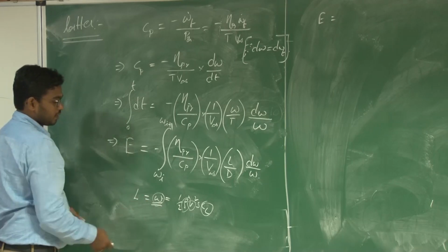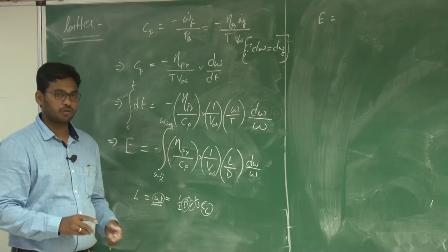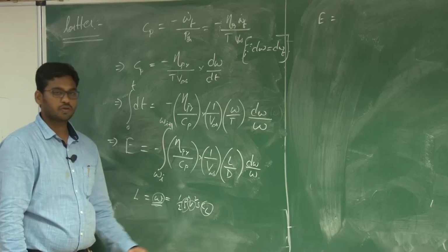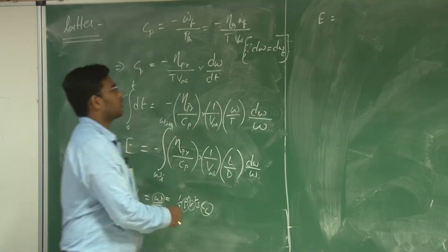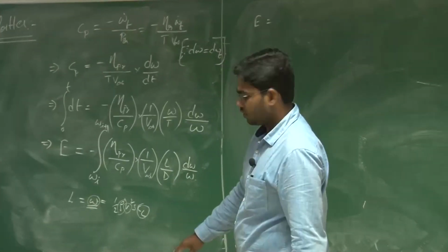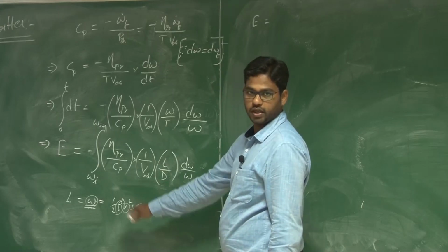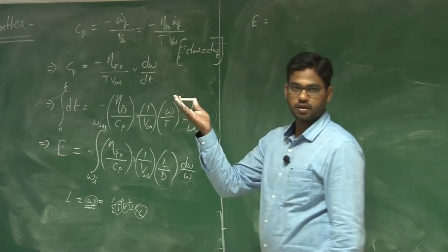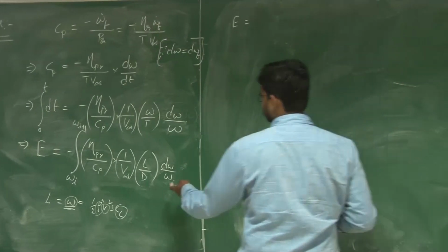So if we consider, assuming that variation in the density is allowed, and V and CL are constant, so this particular term remains constant. So in that case, what will be this equation? So there are two cases, right. Let us solve this for this particular case where density is allowed to change. That means the aircraft can gain altitude as it cruises, right.